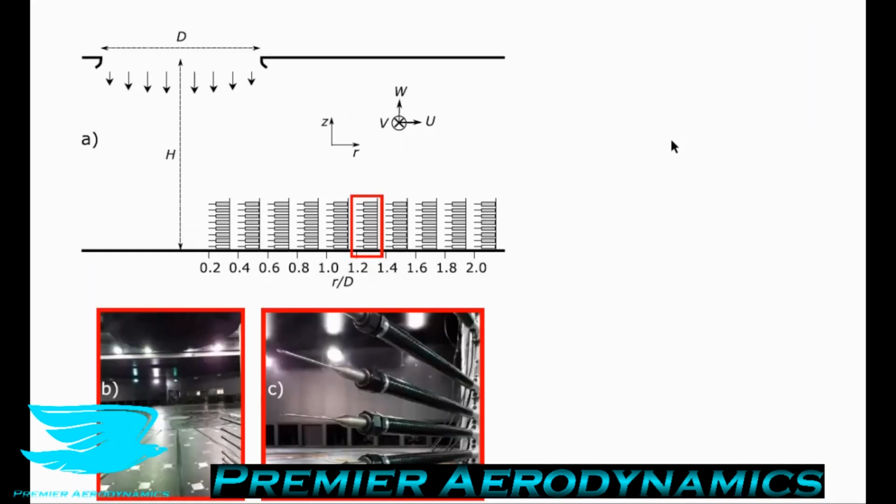So in figure 3, the experimental setup is given. The flow was measured at different radial positions around the center of the jet using these Cobra probes mounted on a heavy and stiff mast that prevents vibrations of the probes in the flow. So this is important when you're looking at the frequency response, because if you have the mast vibrating around, that's going to introduce this frequency into your readings.